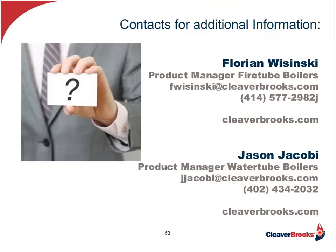This is not an area that, as far as Cleaver-Brooks is concerned, or even our worthy competitors get involved in very much. We depend upon people like NALCO or the chemical treatment people to come in and make the proper recommendation. We can tell them what we recommend in terms of conductivity within the boiler itself, not to exceed so many micromhos or whatever it might be, but then they take it from there and make recommendations on the amount of continuous blowdown and the amount of chemical treatment that has to be added.